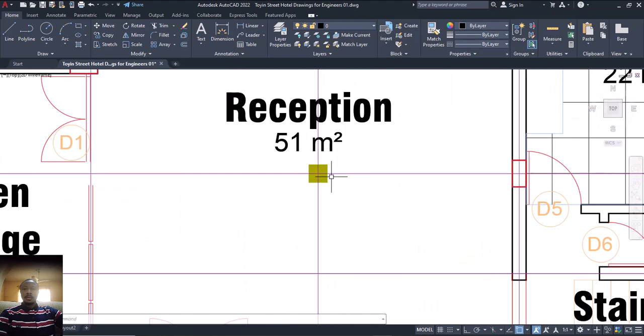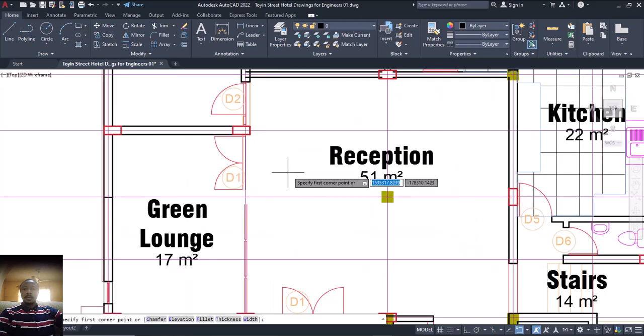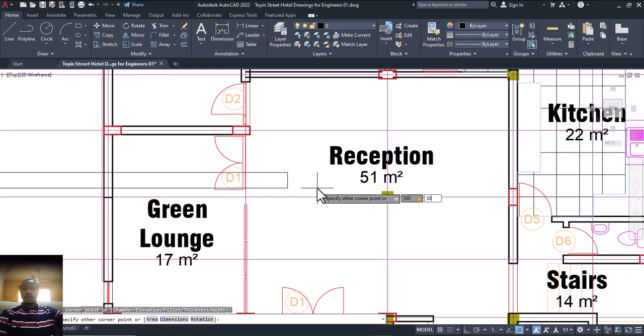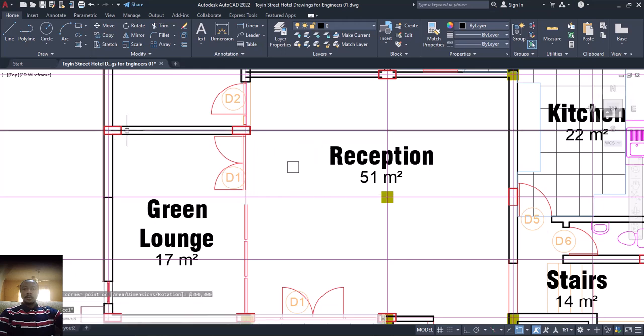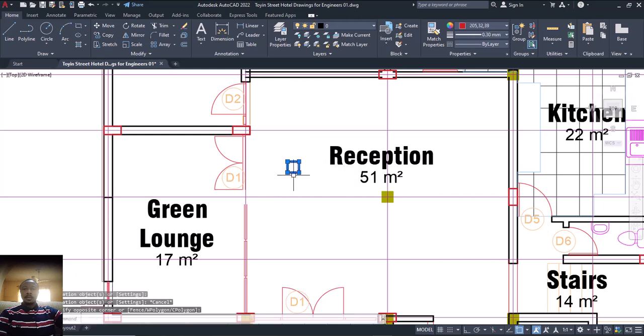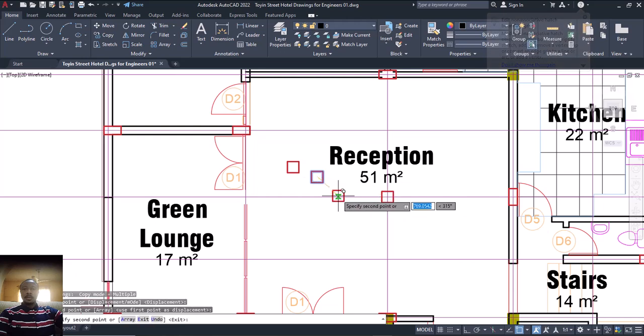This one I'm going to change. Is that okay? Let me play with that. Let me do that now. That's a 300, 300. Enter. Take the properties of this and match it with this one. Then select it, CP, enter, from this point here. Let me just do something. Let me remove this. All right, CP, enter, from this point. I put it to this point. Is that okay? Can you see it?